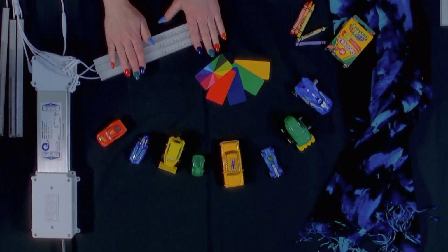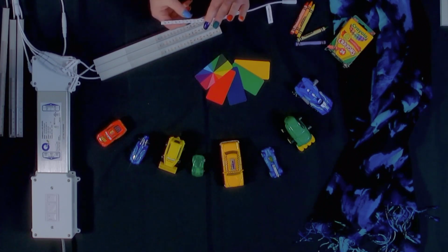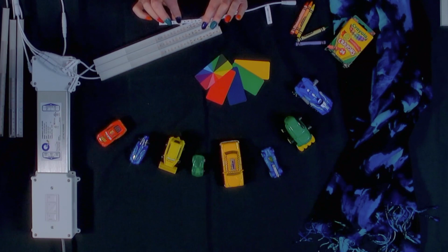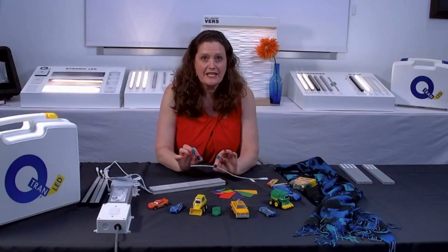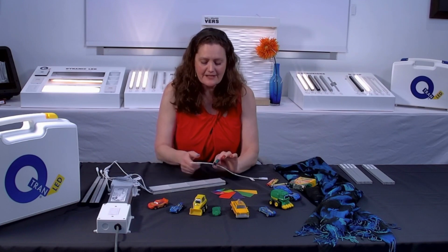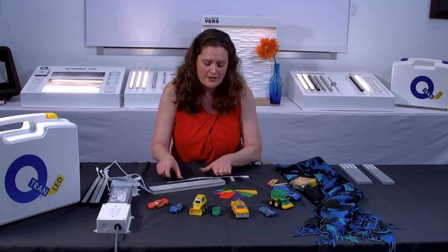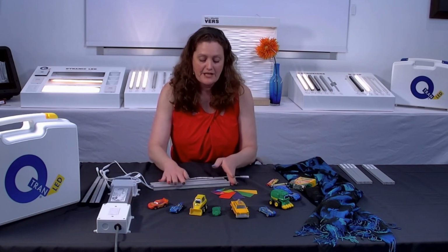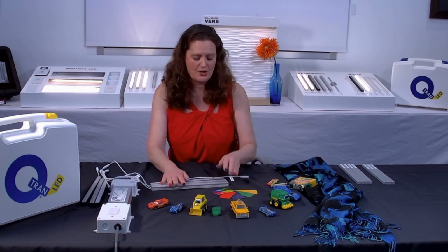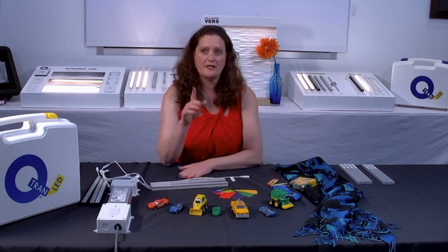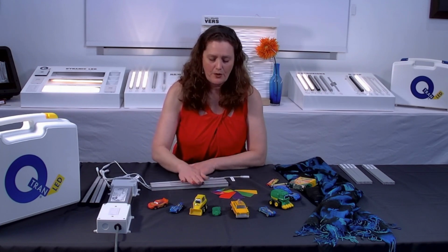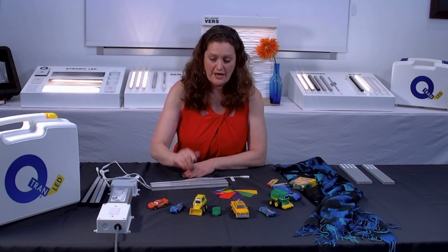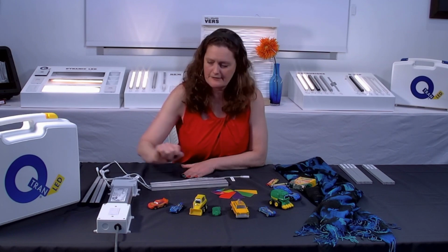So what we've done there is we've engineered the PCB and the resistors, but kept the chip spacing and the chip color consistent. So you're going to get consistent color and consistent dimming across wattages 1.5 to 5. It's also 1 step, 1 bin, which we're going to talk about a little bit more. But I wanted to jump into that before Tyler got to the entire line, because that's really important in our static white series, our SW24 series.